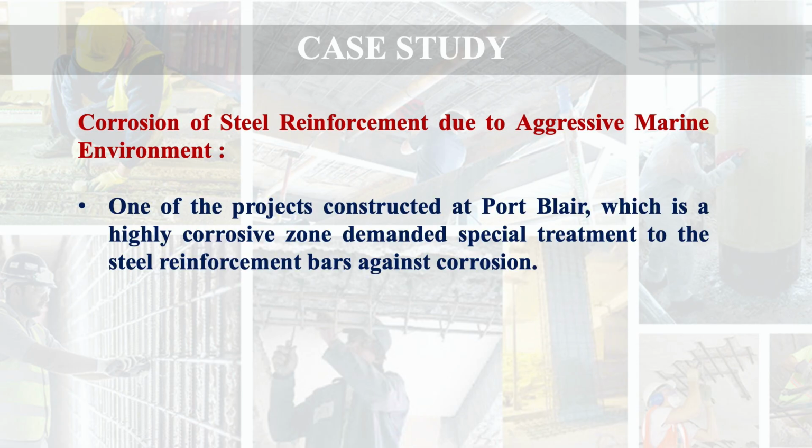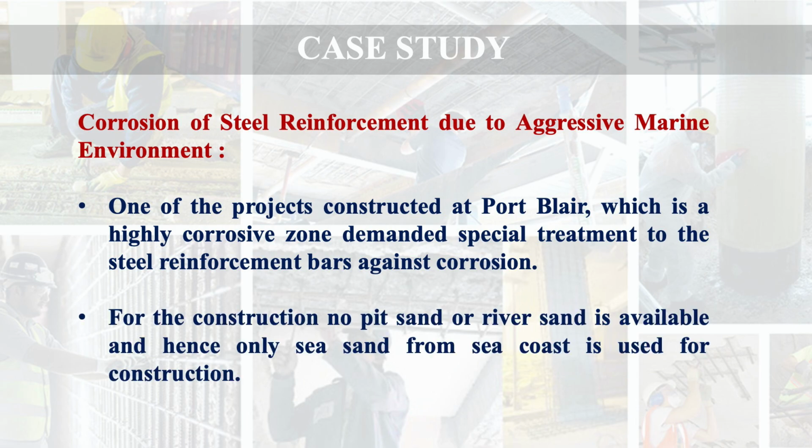One of the projects constructed at Port Blair, which is a highly corrosive zone, demanded special treatment of the steel reinforcing bars against corrosion. For the construction, no pit sand or river sand is available there, hence only sea sand from the sea coast can be used for construction.